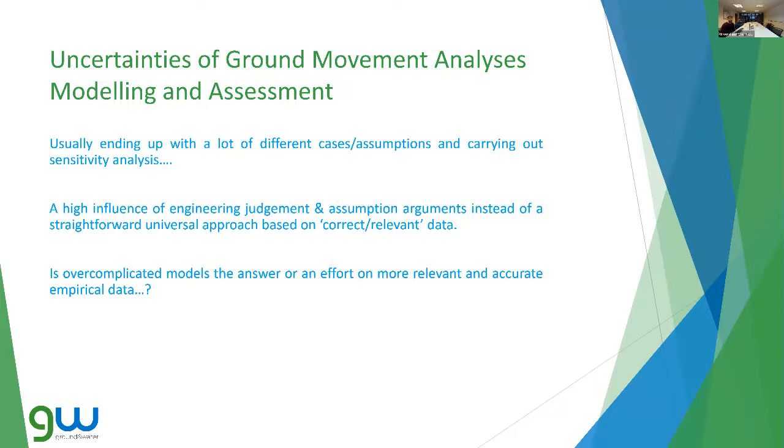And therefore a high influence of engineering judgment comes into play, rather than using just a universal approach based on the correct or relevant data, which, as we discussed before, may not even be correct and relevant, because it may not be the correct geology, it may not be the correct installation of a wall based on the CIRIA curves, because the CIRIA data is quite limited.